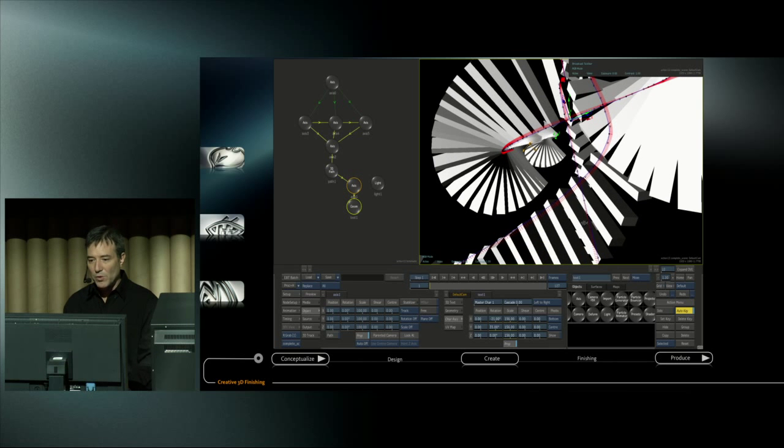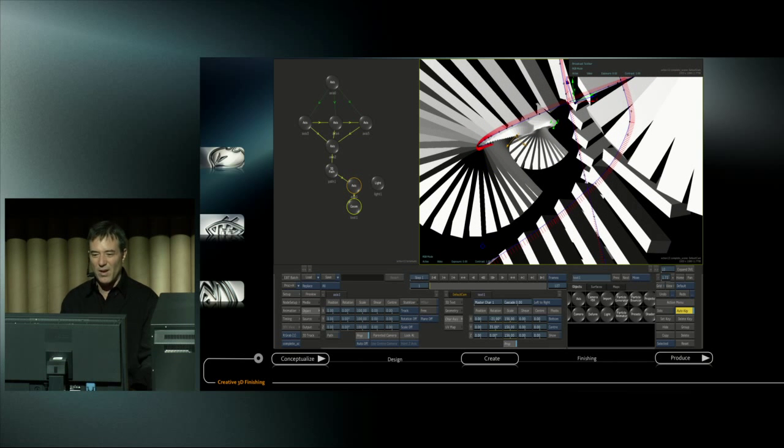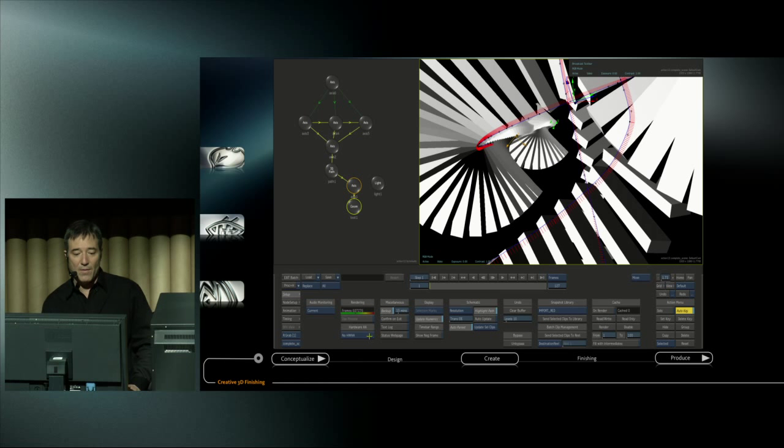But notice what I'm trying to do is create some angles that are kind of nasty angles and things that create a lot of aliasing on the edges of my 3D text. Well, another great new feature, and it speaks to the quality improvements inside of Action in this release. Inside of Batch, you have the ability to utilize hardware anti-aliasing. So notice hardware anti-aliasing options go from no anti-aliasing all the way up to 32 samples. And just by turning on 4, you can see we've dramatically, I'll turn it off again, we've dramatically improved that.